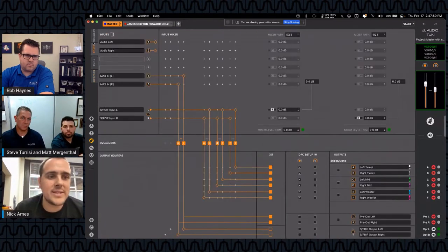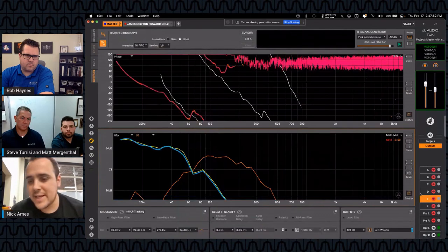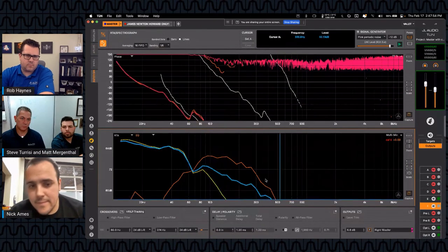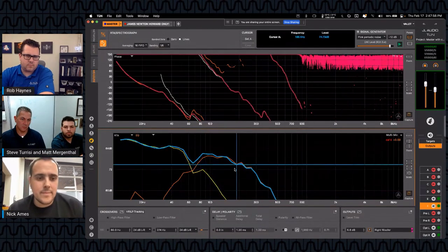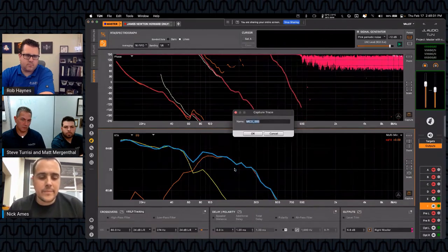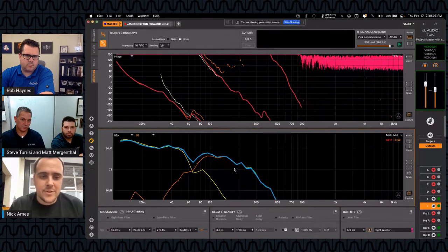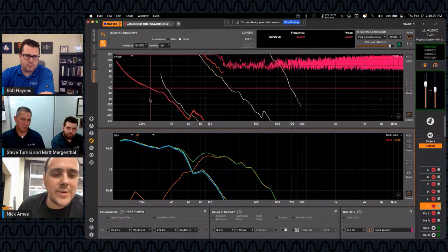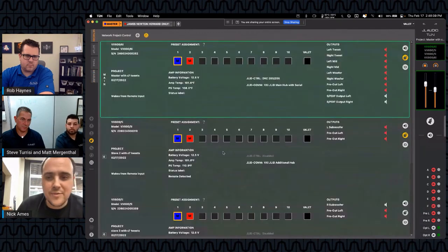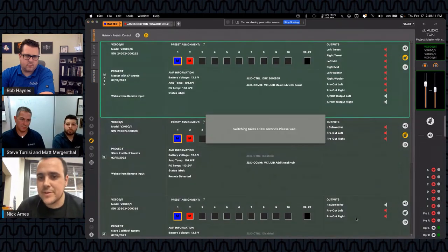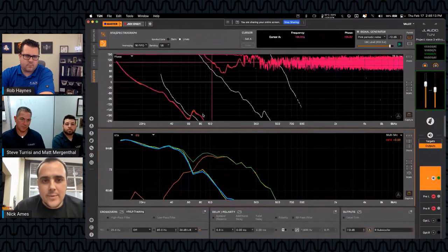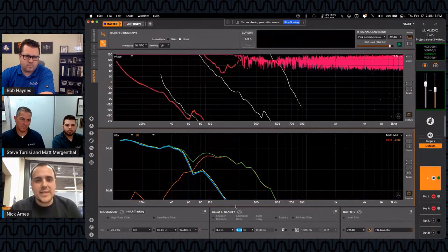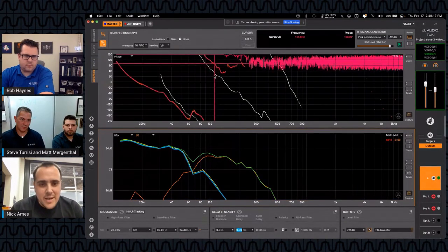Let's actually do that. So first let's capture it like it is. And this is the sum response. Now what we'll do is go into the subwoofer amp that I've unmuted, this one down here, and we will add a little bit of delay to move this down just a hair.